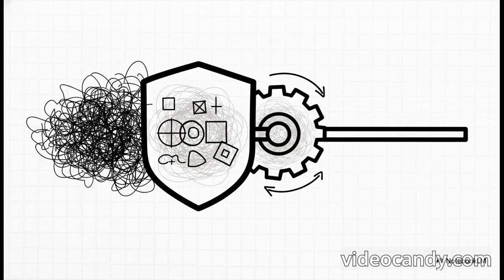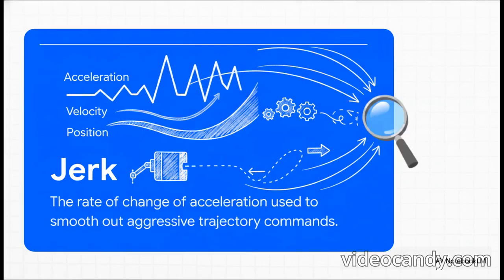Modern premium drives use APC modules to intelligently bypass this conflict entirely. Utilizing feed-forward nonlinear dynamics, APC lets you maintain that massive speed control gain to suppress disturbances instantly, while mathematically identifying and filtering out the specific resonant frequencies of the mechanical load. You get all the structural rigidity with none of the destructive vibration.